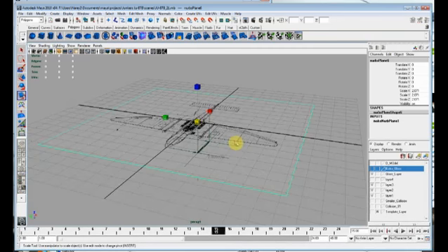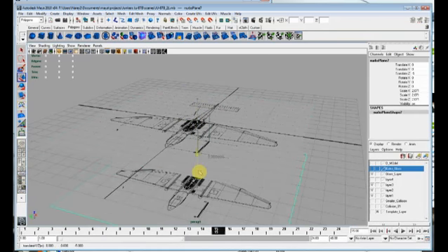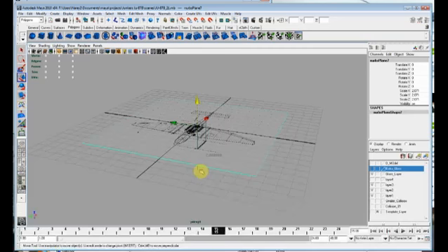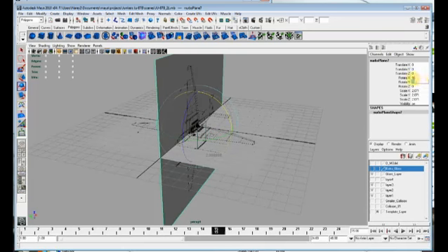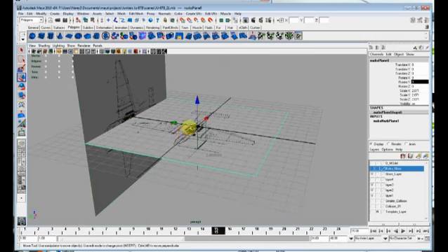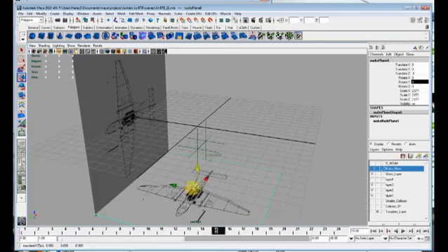So what you do is you turn your grid snaps back on, and you hit Control D and the W key, and now we have a duplicate there. But let's say we want to do a side view, so we just do that. Nudge this in the direction you want the side view to go, then go up to the channel box and hit 90.0 and tab it. And with the grid snap on, you move it out of the way, and you move that down.